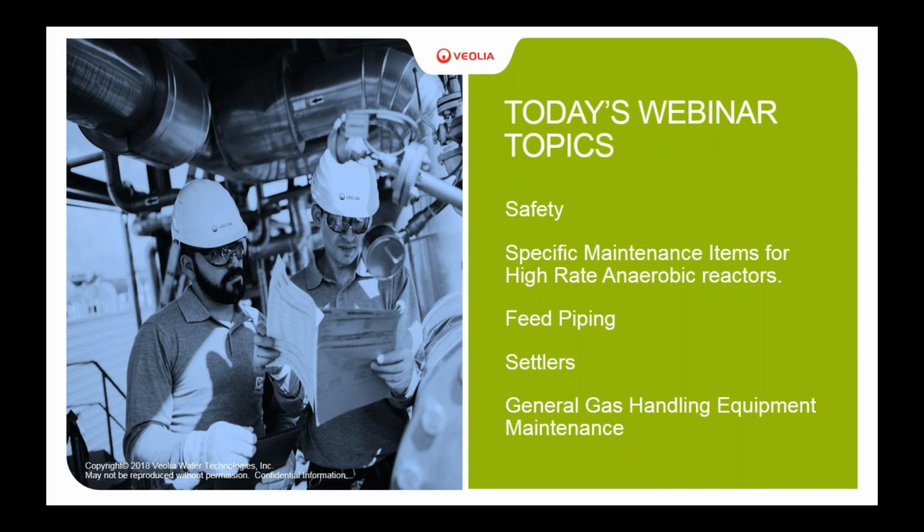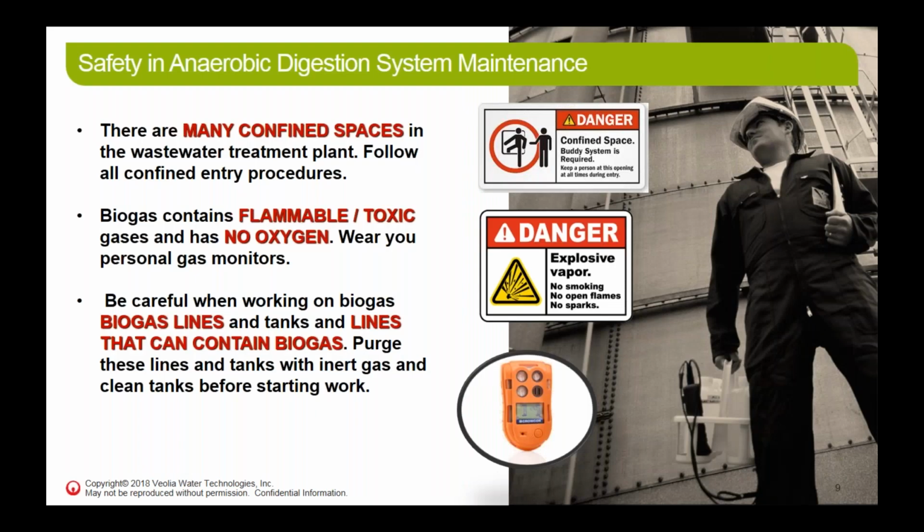So, as I always like to start out with safety. When you're working on an anaerobic system, you do have to take safety into account. It is very important. There are a lot of different safety issues around anaerobic systems. Obviously, in a lot of anaerobic systems, if you ever do go in, they are confined spaces. There's tanks. There are specific confined space entry procedures that you really have to follow, especially if you're doing some downtime and you take your reactor down or you take a wastewater holding tank down, you have noxious gases in there. So it's extremely important to make sure that you follow the proper confined space entry procedures on any shutdown that you take.